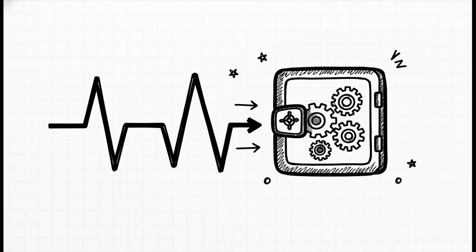Next up, we have the always_ff block, and this one is uniquely dedicated to sequential logic operations. The FF here stands for flip-flop. Now, unlike combinational logic, sequential logic relies on a clock signal. It holds onto data. It has memory.